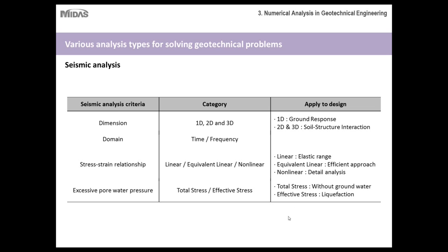And then excess pore water pressure. So when groundwater levels are taken into account for a seismic analysis, you would need to account for effective stress as well as liquefaction, and then total stress to analyze certain parts that don't have groundwater present. So these are all things to take into account for seismic analysis. I won't go into too much detail yet, but later on, I believe one of our courses is dedicated to seismic analysis. We'll go more into detail on how these parameters are used specifically for numerical modeling.